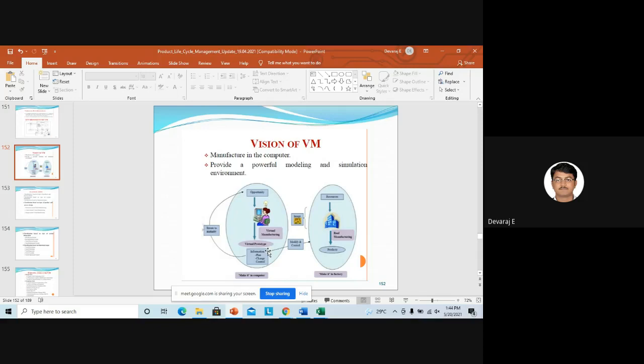They write the CNC program and first execute it in software, whether it is turning, internal boring, or internal and external threading. If everything is correct, only then they will copy the same program into the CNC machine.